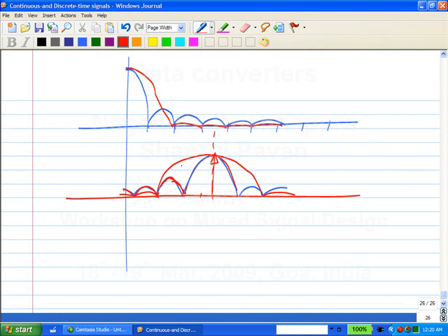Okay. So right next to the sinusoid it is much worse, but far away from the sinusoid it is much better. So that is the trade-off. It turns out that there will always be this trade-off. If you make the window better for higher frequencies so that the leakage energy reduces, just around the sinusoid you will always get a lot of leakage. Okay. What does it mean? What does it imply for the practical case?